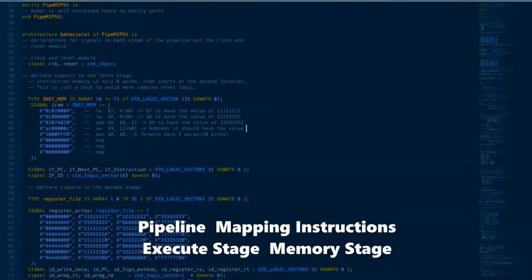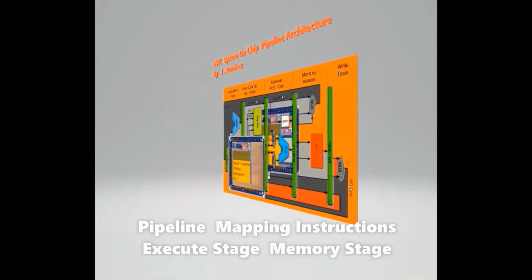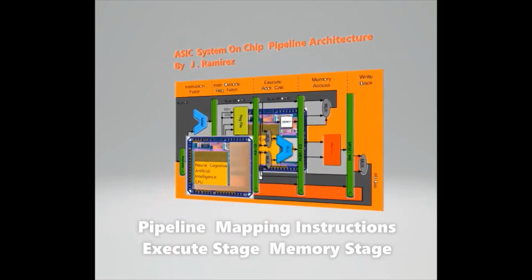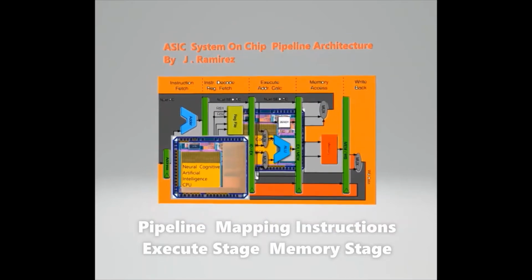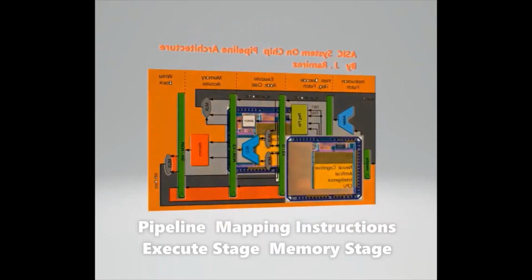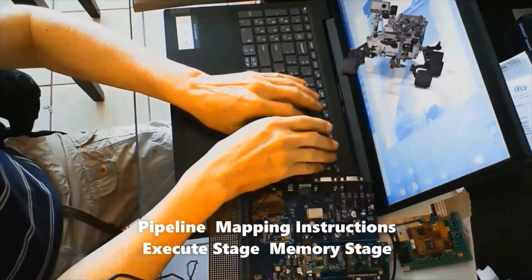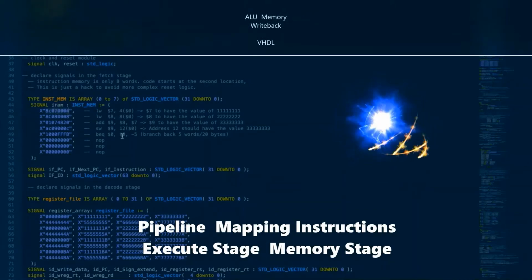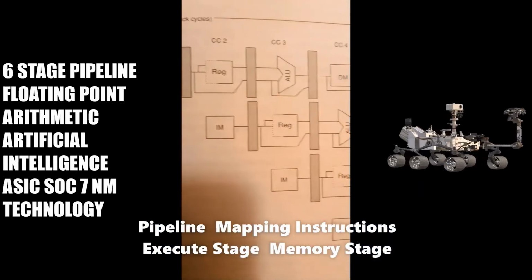The memory stage takes the output of the arithmetic logic unit and puts it into the proper memory location if the instruction is a store. The memory stage contains the data memory object. It connects the data memory to the register bank for the write-back stage to read and also to forward on information about the current write-back register.